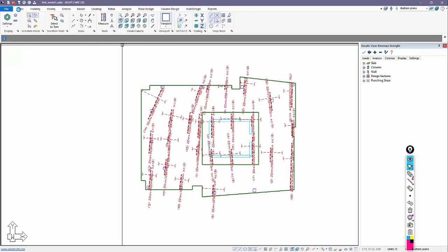If I import a model from Revit, produce the rebar, I can always export the model back into Revit. So that's the only workflow available. I could not import rebar into a non-existent Revit model, meaning a model that the builder model was not created from.